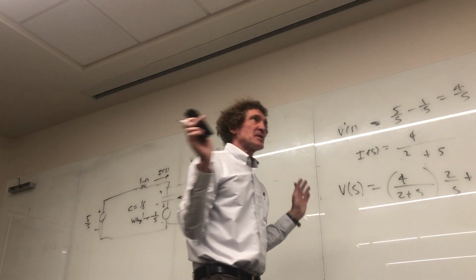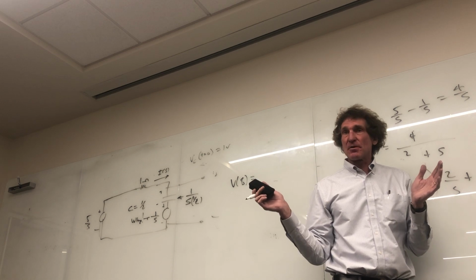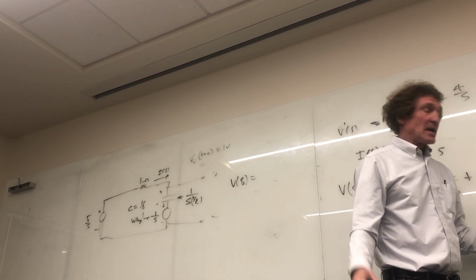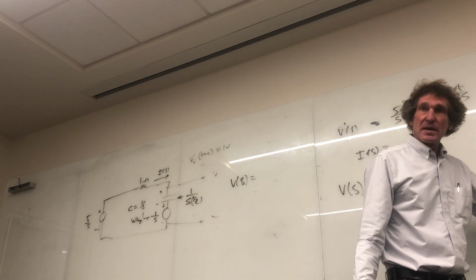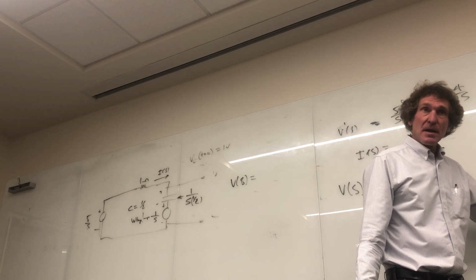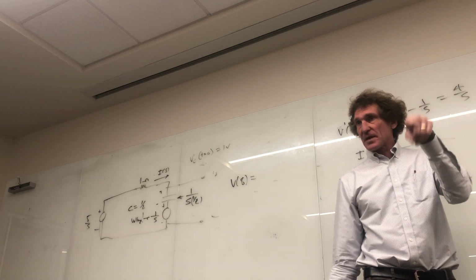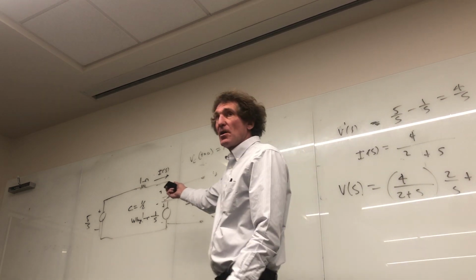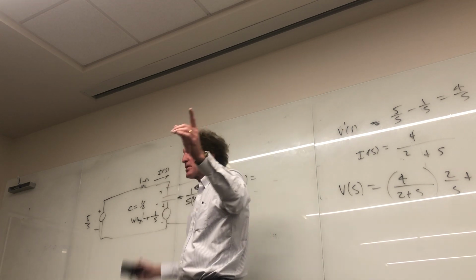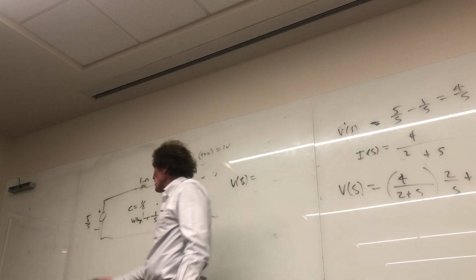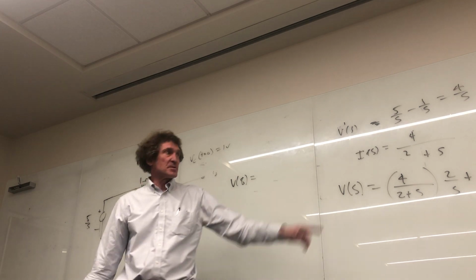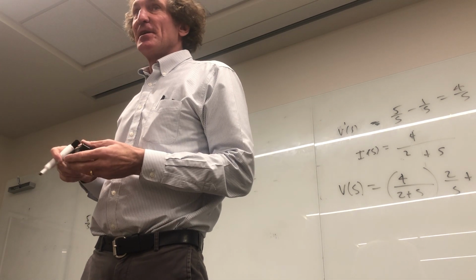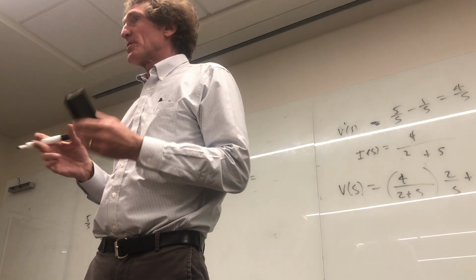The initial state was the voltage was 1 volt at t equals 0, right? So when t equals 0, right at 0 plus, that's 5 and this is 4 because e to the 0 is 1. 5 minus 4 is 1 volt. Checks that box. Where does it go to as t goes to infinity? That's a capacitor. It always becomes an open circuit. In a series circuit, it goes to the series voltage, which is 5 volts. Yes, checks both boxes. That's how you do the problem, using the initial conditions for the capacitor.